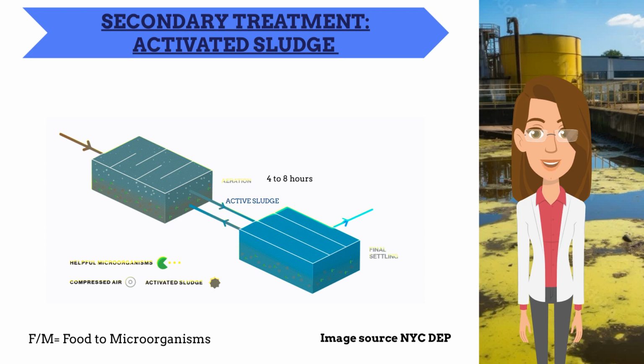This process must be meticulously monitored and controlled to maintain the proper ratio of substrate, or organic load, to microorganisms, the food to microorganism ratio. The waste rate, or wasting rate, determines the F/M ratio. The higher the wasting rate, the higher the F/M ratio. Hence, a lower F/M ratio means the microorganisms in the tank are starving, which results in more efficient wastewater treatment. Important parameters are as follows: organic loading rates, oxygen supply, and control and operation of the final settling tank.